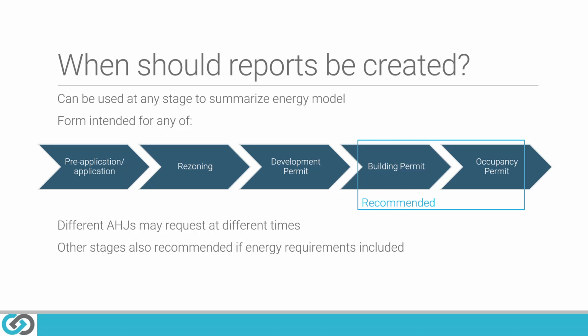But at least the building permit and occupancy permit submissions are recommended because that aligns with what was requested in 2.2.9.2 of the BCBC. Now, if energy requirements are included at other stages of the process, then it would be recommended to submit the form at that stage as well.